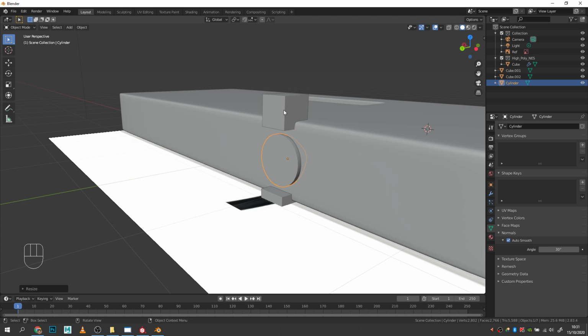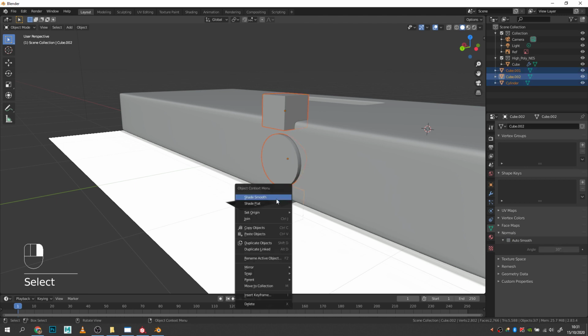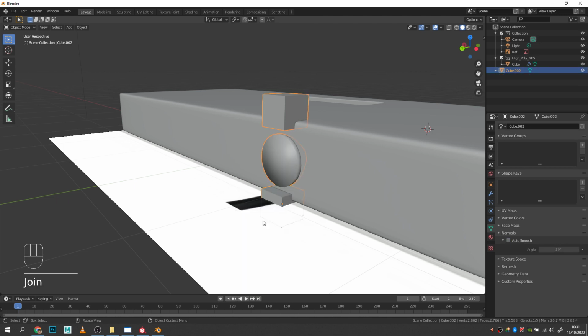These cutouts, I'm going to combine them together. So I'm going to hold down Shift to select more than one. And I'm going to right click and choose Join. Just going to have a quick sip of water. Now you notice when I joined them together, they've taken on the properties of the first object. So our auto smooth's turned off. So we just need to reapply that.